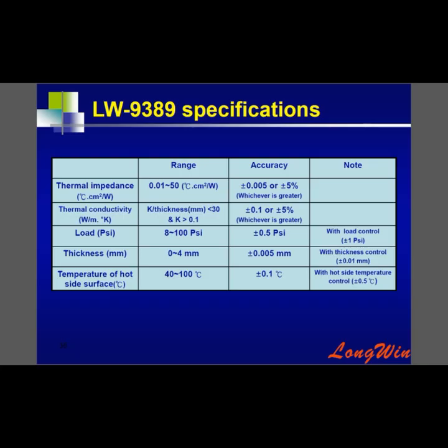So right here, we can consider the thermal impedance 0.03 to 0.04 could be thermal grease with good performance. And regarding the deviation, actually 0.03 and 0.04 could be at the same level. So here we define the deviation is plus minus 0.005.